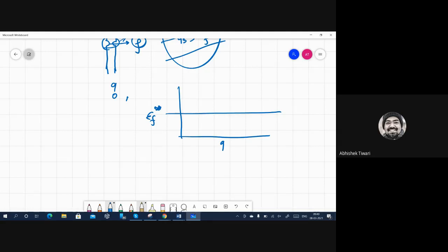So if my fracture strain value is something, let's say this is 0.2, then what should be the value of triaxiality I should give? So triaxiality will actually have infinite values. This is similar to ideal plasticity.